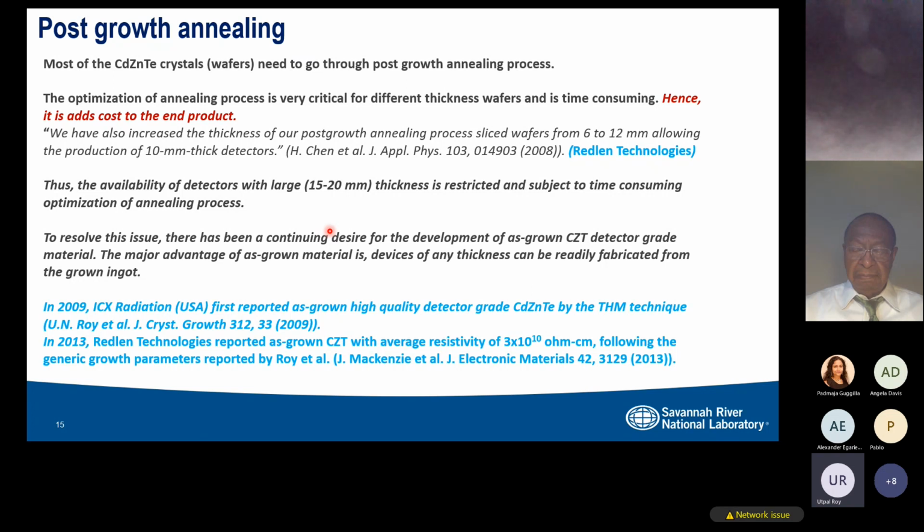The moment you put the glass inside the boiling water, the surface will see the temperature of 100 degrees centigrade, but inside the glass, it will take some time to reach that temperature because the thermal conductivity is very low. That means you are basically creating a very high temperature gradient within the glass.